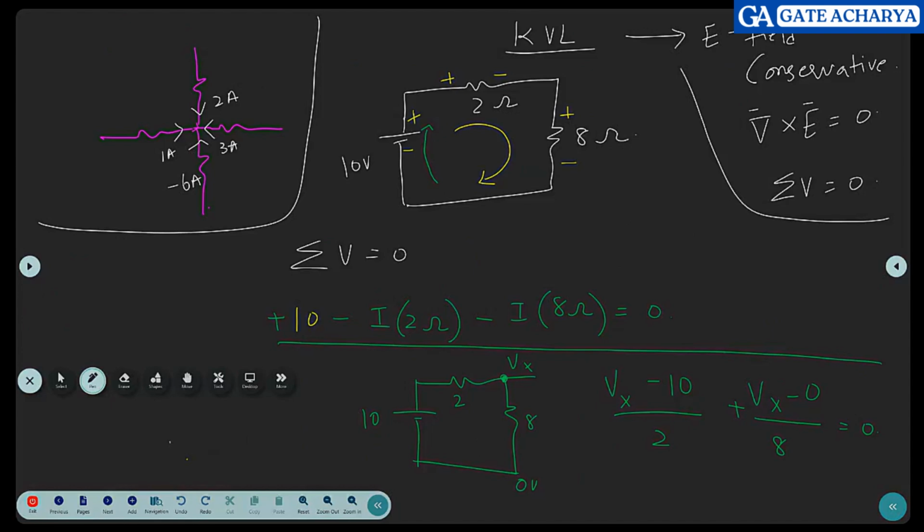So what will be the voltage there? 8 volts. Can you solve the left top with KVL? Do you think you can solve it with KVL? There's no loop. If there is no loop, can you solve it? No. You see how KCL is bigger than KVL. You can use KCL anywhere. KVL has some limitations. So from Vx you can find everything else you need. Basic KCL, basic KVL.